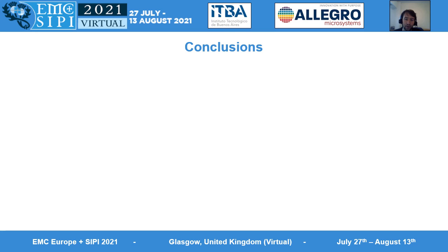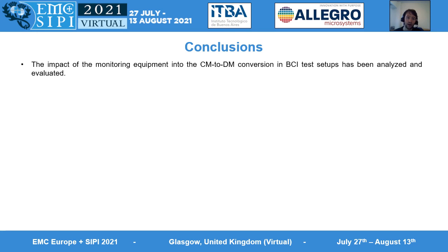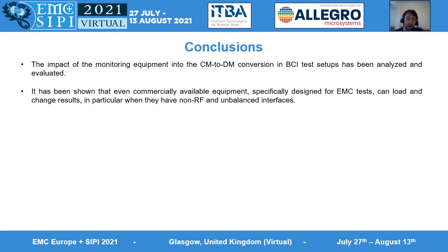And in order to sum up, we have shown that the monitoring equipment can impact the common mode to differential mode conversion in bulk current injection tests, and we've analyzed and evaluated different mitigation strategies. We've shown that even commercially available equipment specifically designed for EMC tests can load and change results, in particular when they have non-reference and unbalanced interfaces.